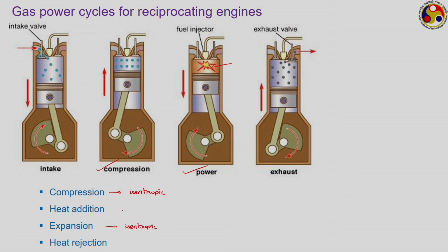If we are assuming the heat addition process to be isothermal, or I should say reversible isothermal, and similarly the heat rejection as well to be reversible isothermal, then what do we get? This isentropic compression and expansion, with reversible isothermal heat addition and heat rejection, is of course our most ideal cycle, which is the Carnot cycle, where heat addition and heat rejection processes are also externally reversible, as we are considering reversible isothermal heat transfer with infinitesimally small temperature difference between system and surrounding.